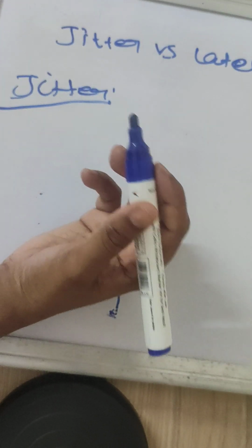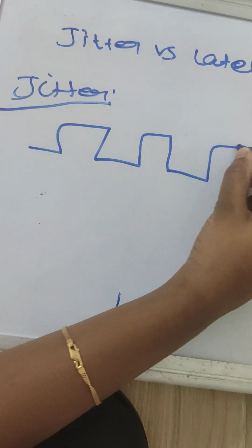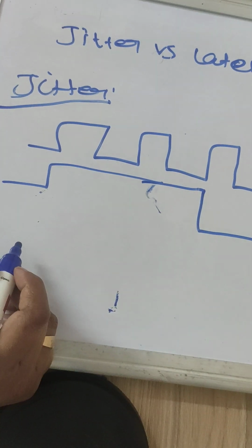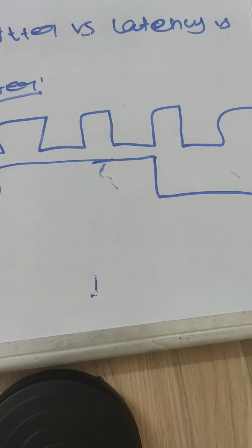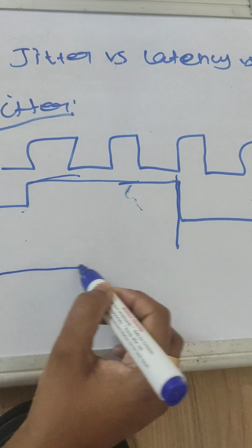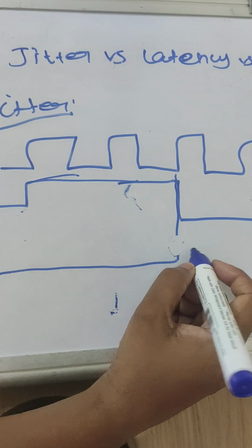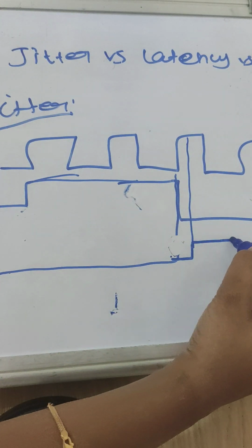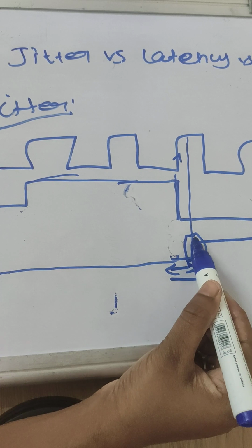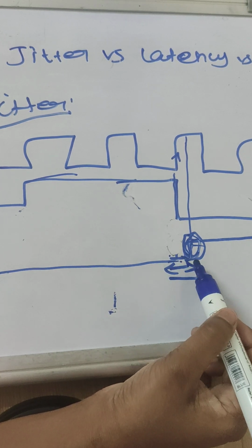But this is that unusual delay, the delay which is introduced by the channel or something. If my clock is this and my input is this, the same as I am expecting, consider there is only one delay. You will be expecting this particular high at the output here, but due to some system or electrical characteristics, your input is just delayed here. This shift between your actual active edge and the place where your input is getting shifted happens because of the channel characteristics.